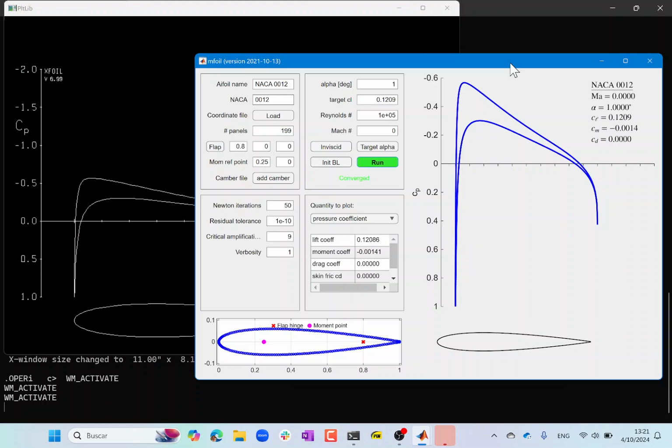Okay, it's a function that is pretty much 0 at the trailing edge, right? Just think about the gap. The gap is basically the distribution of lift, right? Basically, if you have a bigger gap, you have more lift at that chordwise location. It's pretty much 0 at the trailing edge, goes bigger and bigger, and it peaks very close near the leading edge,